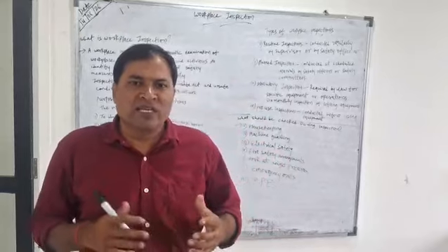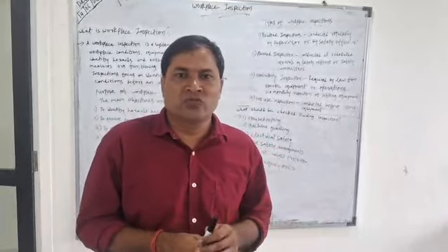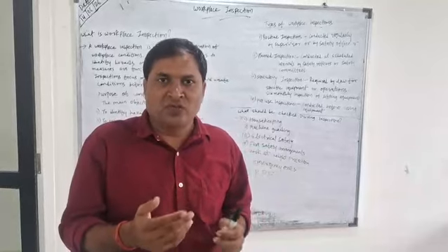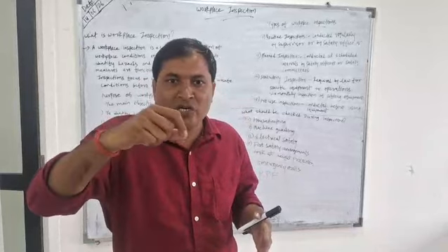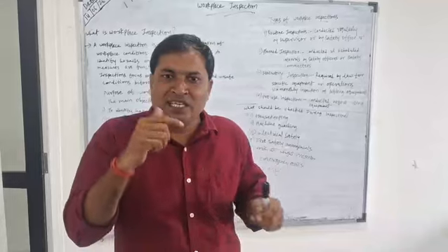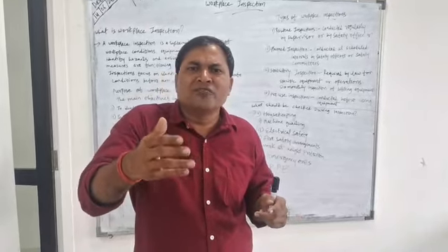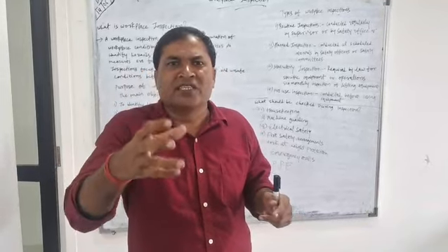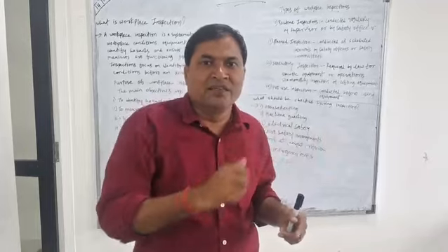Workplace inspection is very important. While workers are working, they have to go with the checklist. You have to follow the checklist, and then you need to ensure the safety of the electrical wires. There should be no damage, no cut. And you need to check the inspection related to the machines operated by the workers.